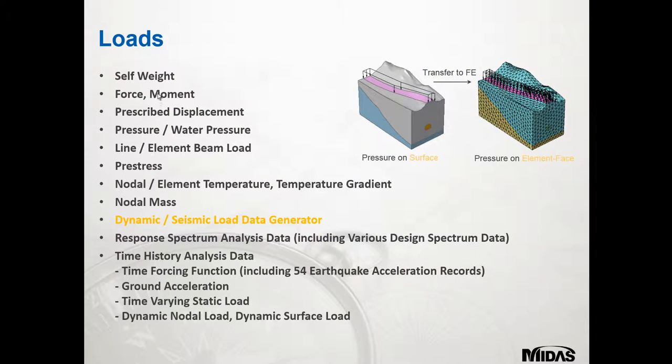loads. As you see, a comprehensive list of loads from self-weight, forces, moments, prescribed displacements, pressure and water pressure, all the way through to the dynamic seismic load data generator, response spectrum analysis, time history analysis, and the time forcing function as well, including 54 different earthquakes. Here you can see the pressure on a surface and also the pressure on elements. It doesn't matter if it's a planar element or a mesh surface, we can still attribute the loads to it, and we can transfer the loads from the standard loading over to the finite elements.